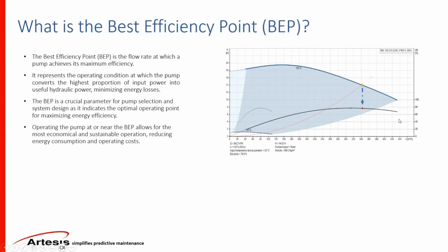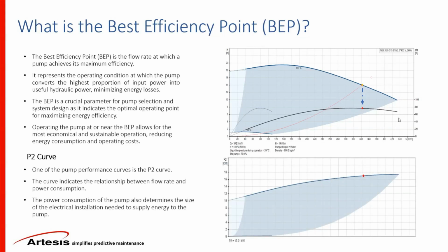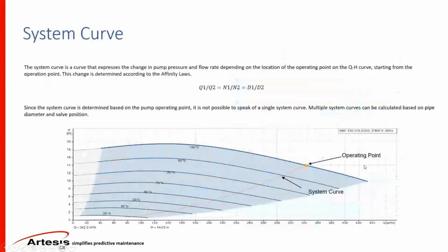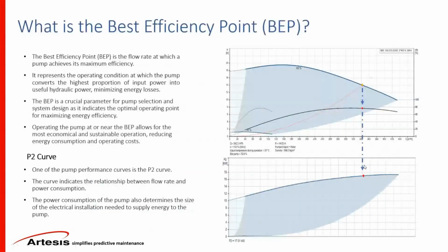So having the efficiency curve will, of course, help us determine, again, the performance and efficiency of the pump. And through the P2 curve, which is the corresponding point to these points, will help us, again, to keep track of the power consumption.